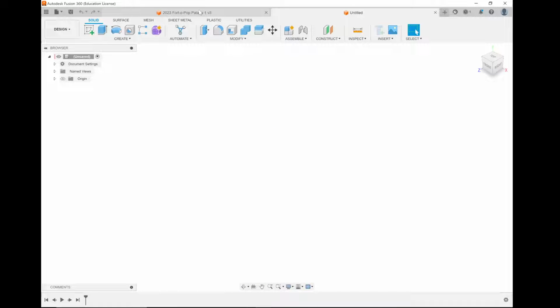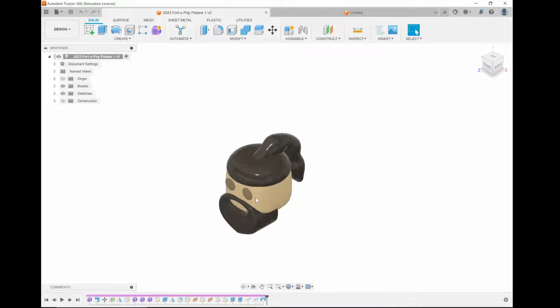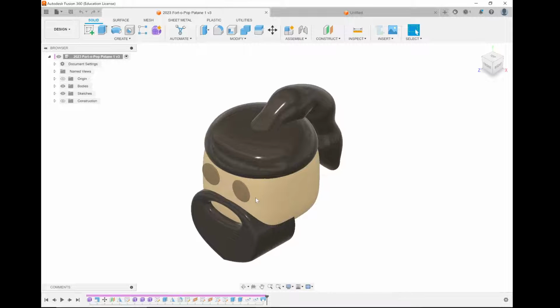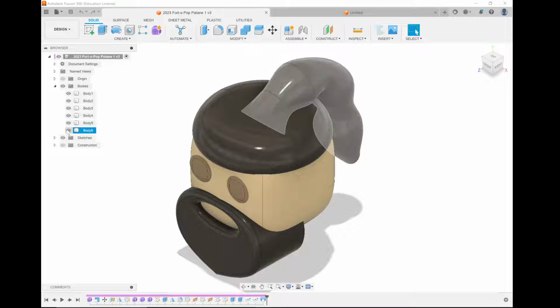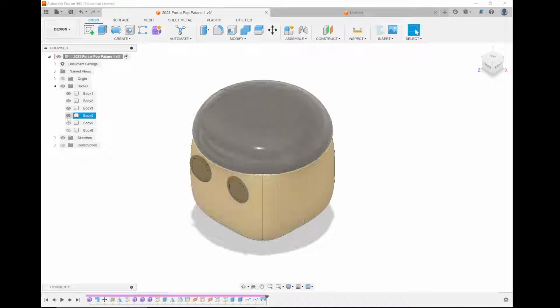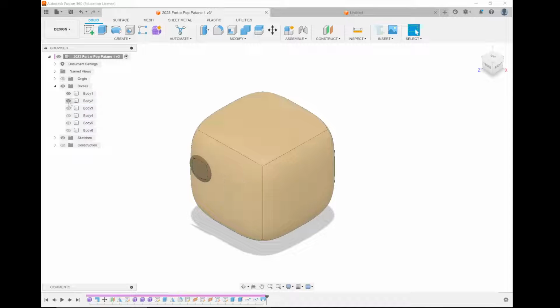All right, so if we look at this example of the Funko Pop we have here, some features in here make sense that we've seen before. If we look at the beard, this is a 2D image that's been extruded into 3D. We've done examples like this before when we did our bridge. This part here is a revolve tool, but we have a lot of surfaces that we haven't seen before. If I hide the hair, all right, we'll see this over here.